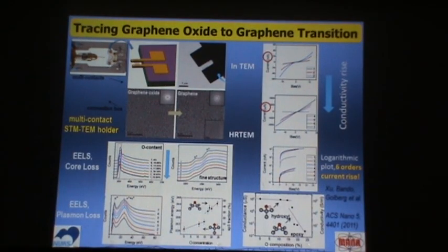We can bend them as many times as you want without breakage. And the good thing, the tip is only 1 to 2 nanometers thick. It means that by using this simple tester, we can individually measure the electrical resistivity of grain boundaries and grains in ceramics and in metals. And we have these ongoing projects these days in Japan.